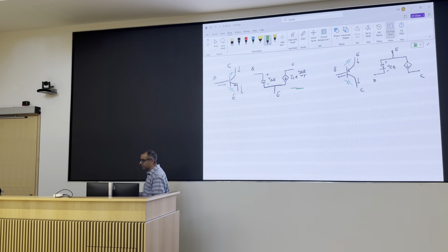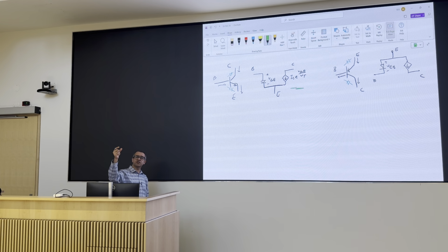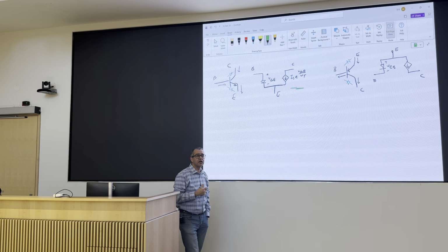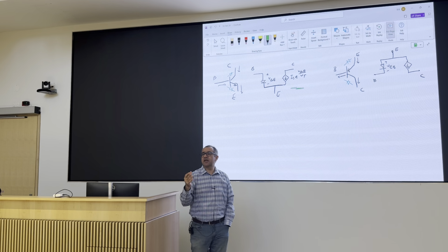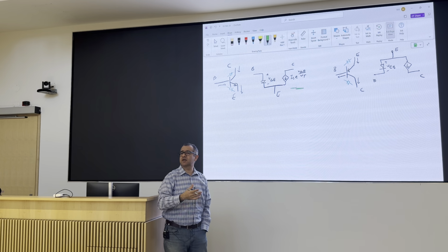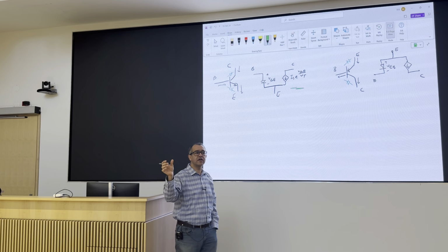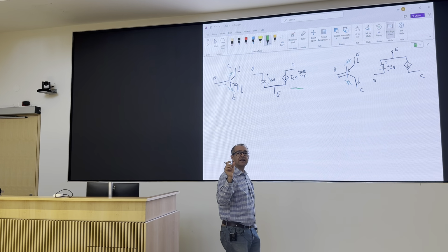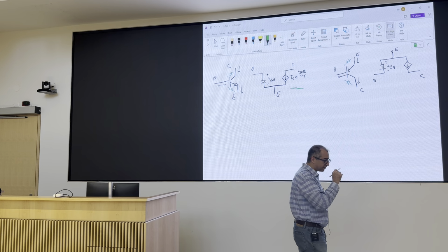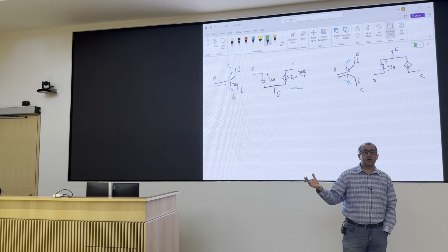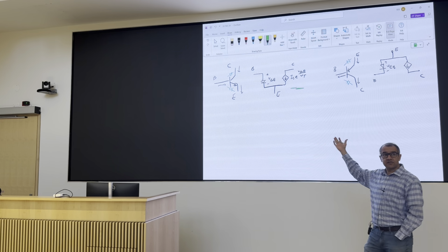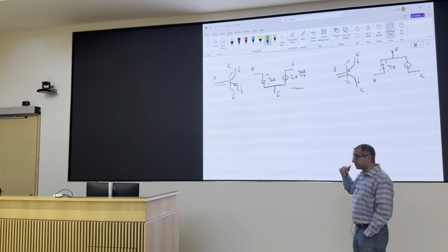But we also remember from the diode discussion that the voltage drop across the diode when it is on has a very limited range. For measurable currents, it's somewhere between 0.5, 0.6, 0.7, 0.8, somewhere in that range. It's a relatively small range of values for that VE on. Same thing applies to BJT. You have two diodes, same issue, right?